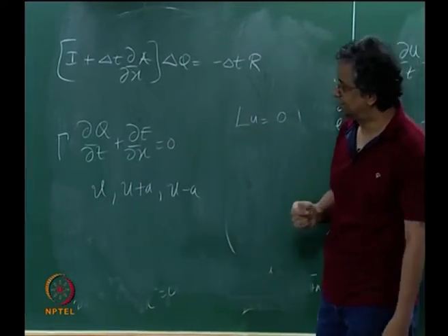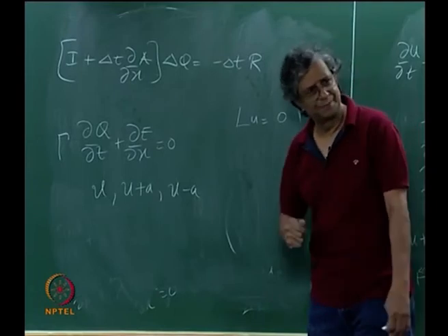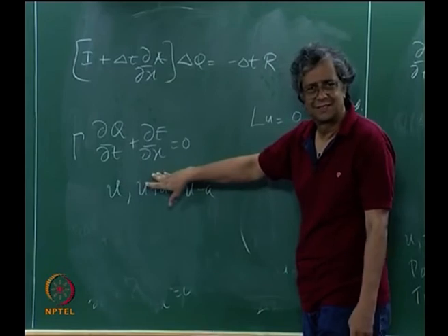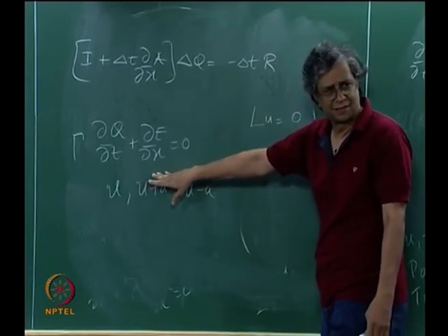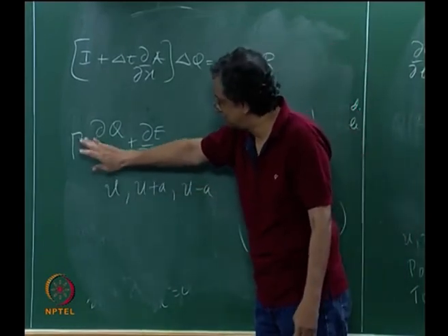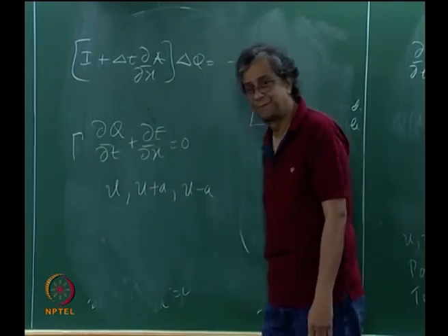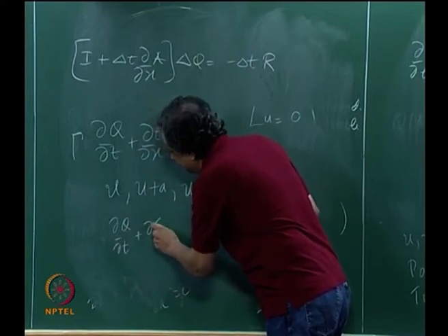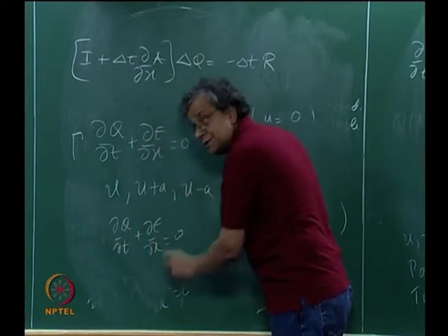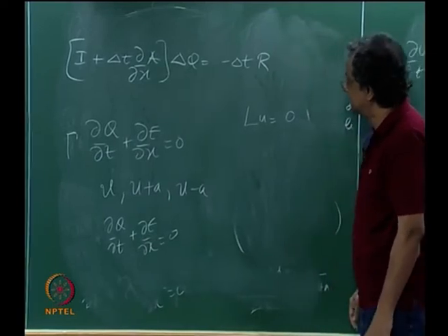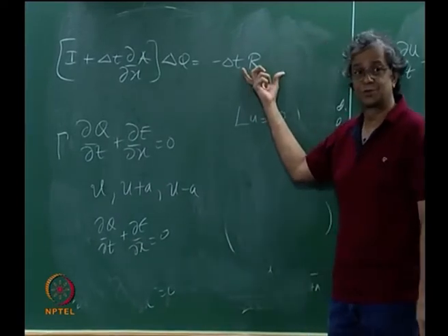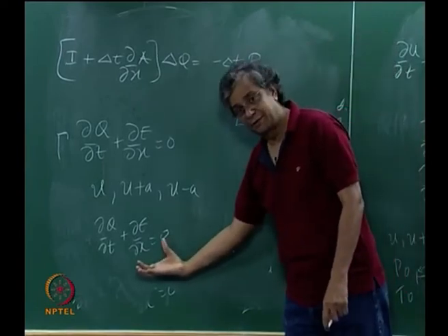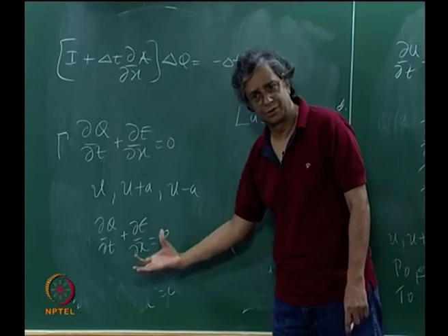Then of course we looked at unsteady flows by adding a pseudo time term, right. Of course you can solve this directly using, I think post my demo I did the Runge-Kutta method, right. You can solve this equation without the gamma, of course, if you are looking for the unsteady solution; you can solve this directly. So if you are looking only for the steady state solution, this is called a time marching scheme. If you are looking for the transient, we are looking at a time accurate computation.